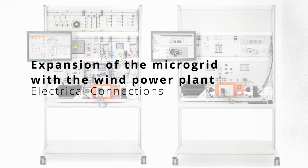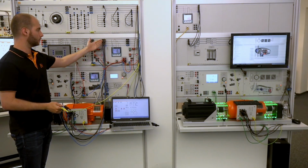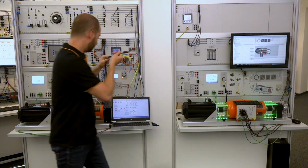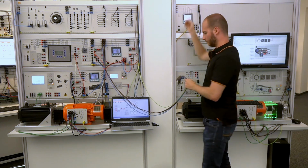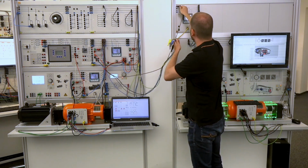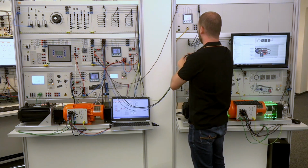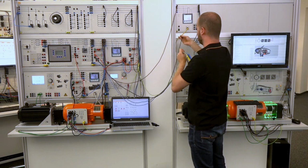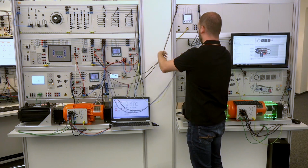After configuring the communication, the electrical connections must also be established. The wiring must be prepared before starting the generators. You can find the wiring diagrams in the respective LabSoft courses. Connect the three phases, the neutral conductor and the protective earth between the generator busbar and the power quality meter of the wind power plant. Both systems are now ready for coupled operation.